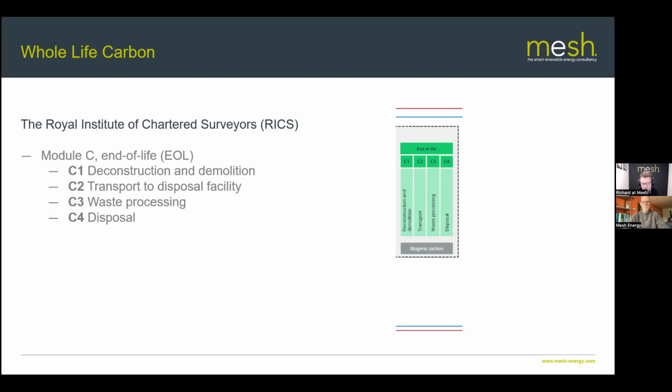Ideally, and we've worked on projects like this, they would use recycled brick, so you can classify the brick as being reused as a material. And similarly for timber as well. The default position for timber, for example, is incineration. Now, if you can design a building where the timber is designed for disassembly, and most of the timber can actually be reused as timber, then of course it reduces the carbon impact at the end of life of the building, and then of course there's the disposal.